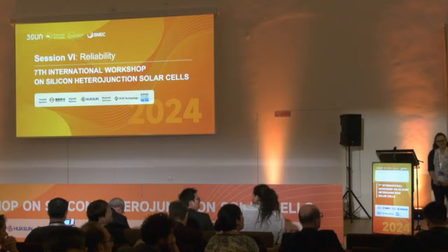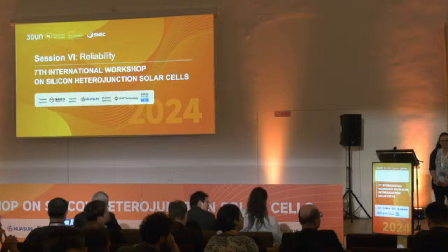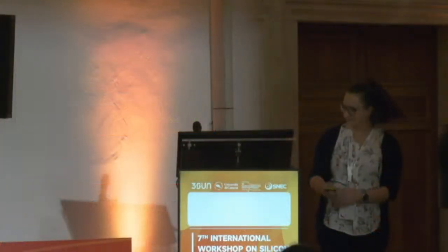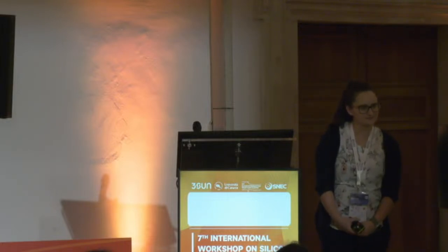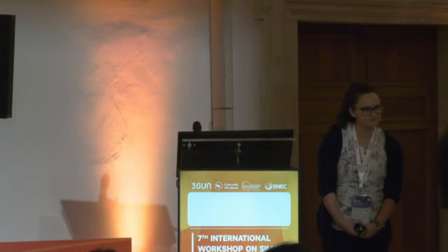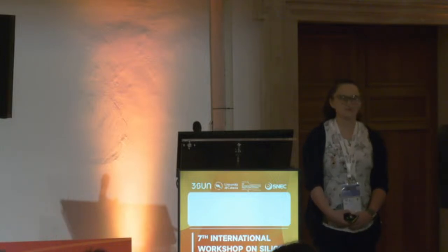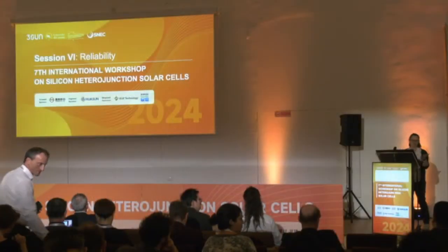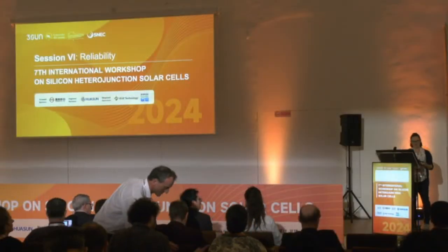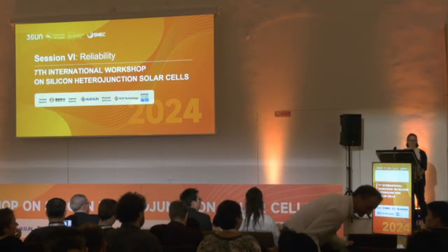Thank you for the nice talk. You showed that there is a SiOx or a SiO2 forming at the TCO silicon interface. But do you see series resistance increase or fill factor decrease? There is a fill factor decrease and an increase in series resistance as well. So we're wondering if this same feature is causing the increase in series resistance and the voltage loss at the same time.